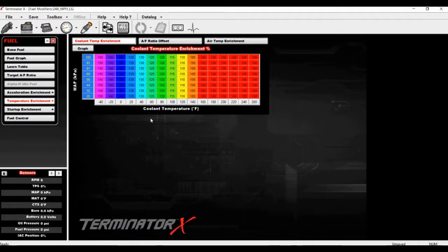Spark ignites the air-fuel charge and is completely related to the amount of available energy, and that includes how much energy is in the head in terms of heat, and how much energy is in the block and head in terms of water. It's a sum total of energy that will ignite the air-fuel charge. So whenever you are cold and you just started the car, you need more fuel to give that spark more opportunity to light.